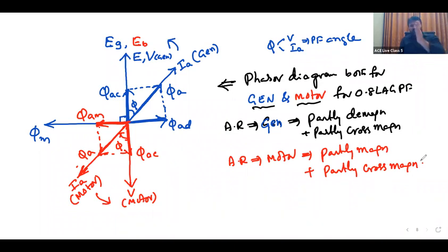So everywhere I have shown only lagging power factor, and everywhere if you just change the current direction, the current phasor, then armature reaction is quite opposite. For ZPF lagging, alternator is purely demagnetization, but motor it will be purely magnetization. When current is in this direction, for motor the current is in the opposite direction. So let me give the table instead of drawing many diagrams. Yes, you are going to write competitive examinations, conclusions must be known.